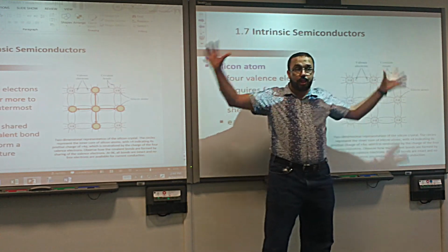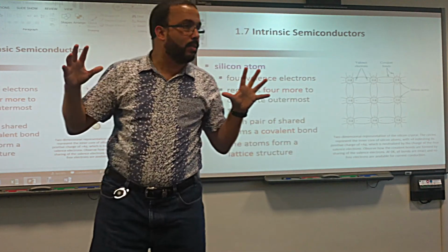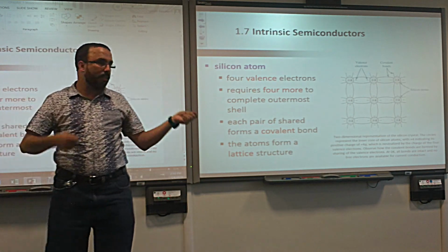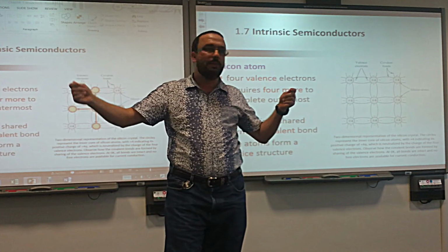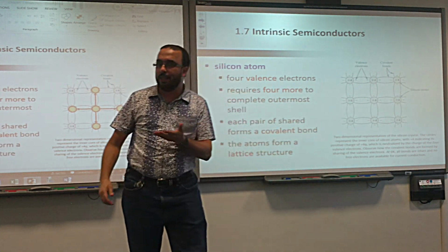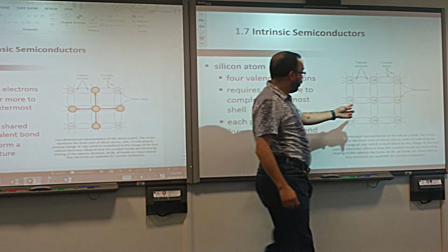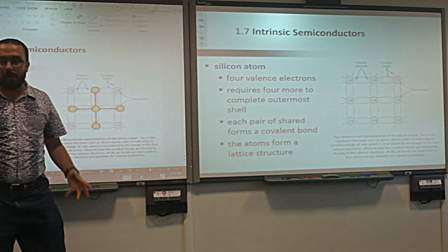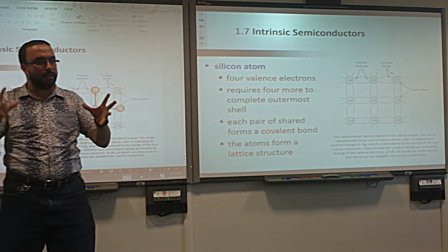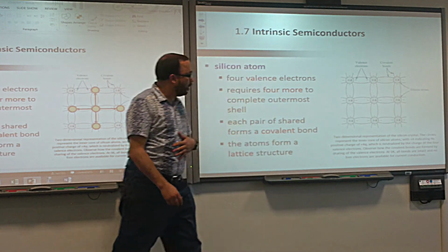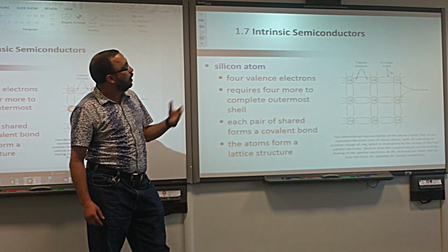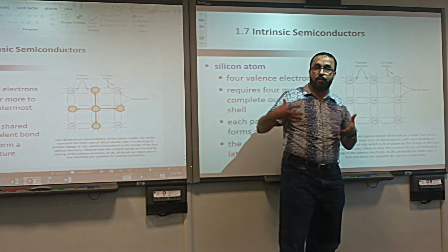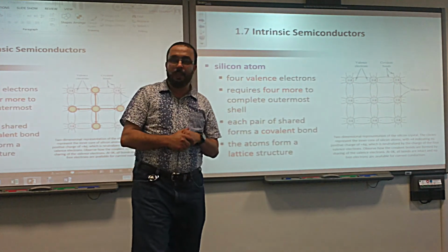In the outer shell of the silicon atom, it has 4 electrons. 4 what? Electrons. So it can create how many bonds? 4. Because each electron can be given to the next silicon atom, and we create a bond, and that's what is happening in the silicon crystal. So they create bonds. Here 1, 2, 3, and 4. Bingo. So these are the bonds that make the crystal. Do you understand? That's it. We call this an intrinsic semiconductor, meaning the property of being a semiconductor is made out of the silicon itself, out of those atoms making the crystal. We call them intrinsic.